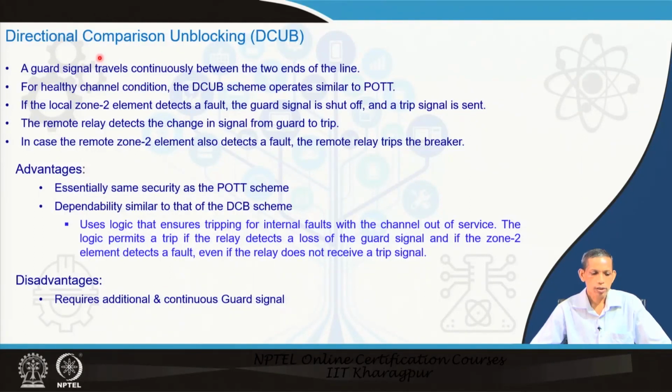The last one is on directional comparison unblocking. Earlier we were talking about blocking, now it is unblocking. Unblocking means you can say that it is a trip kind of thing. What is being done here? A guard signal travels continuously between the two ends.